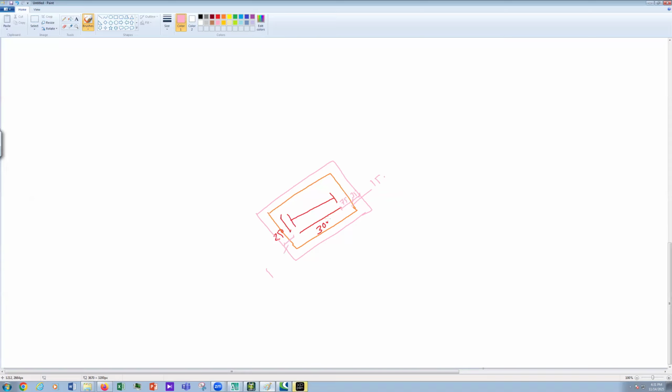So your steel column is 300, plus this side 75 plus 75, 150, and this side you also have 150. So what is the value? The value is 600. So the length of your preliminary RCC column will be 600.